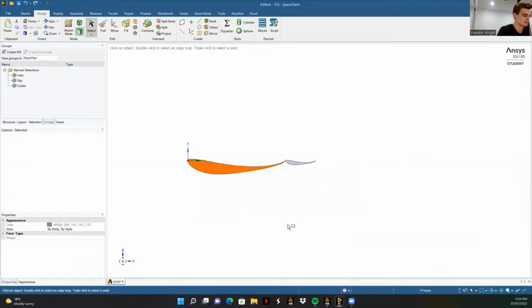So this one here is going to be the first element. Just click and box select the whole thing. Make sure you get all 4 faces. That makes it so much easier. I did that face by face for several weeks. It's a waste of time. Anyway, so name selections are now done. Now we are going to move on to using the Move tool to create our parameters.